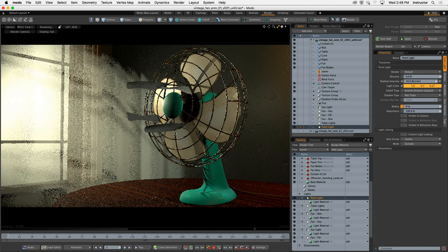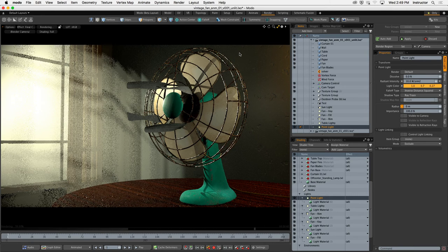We want to try to light as much of the scene as we can with direct light sources. We don't want to leverage the power of the indirect lighting system yet, okay? If we can get as much coverage with direct lighting, we're there. That's the goal, okay? The render engines, all render engines are built for direct light sources. The technology for indirect is just to kind of fill in the shadows and start integrating all of this, okay? Not to provide general illumination inside the scene.